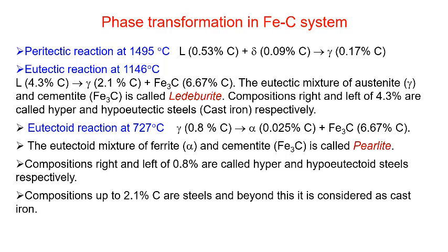So that particular mixture of ferrite and cementite, that eutectoid mixture of ferrite and cementite, is known as pearlite. Okay, and this forms in a particular morphology also. I would have shown you for the eutectic also that it forms in a particular morphology, taking what is known as a lamellar kind of structure, where you see these lamellae of these two solid phases existing together in some colonies across the material, across the microstructure.